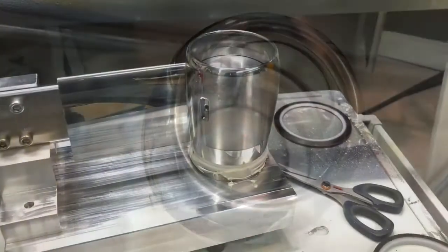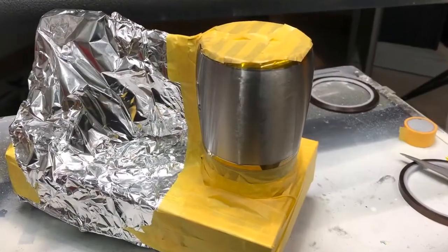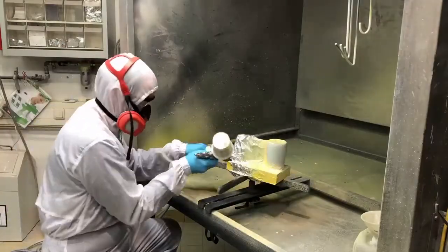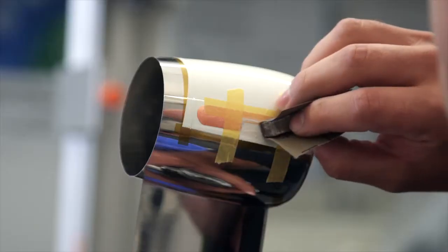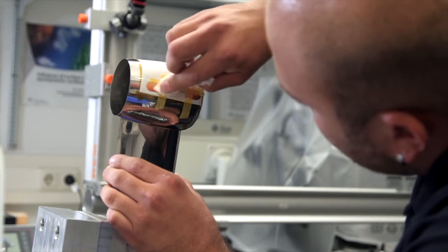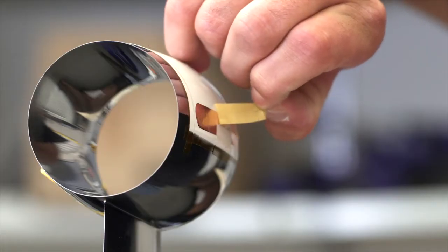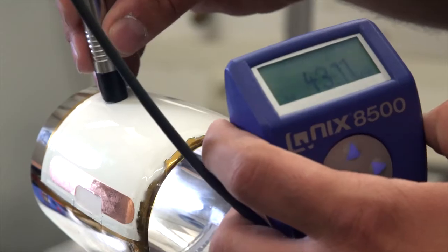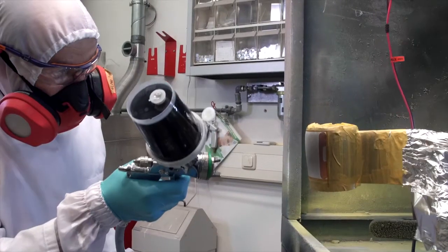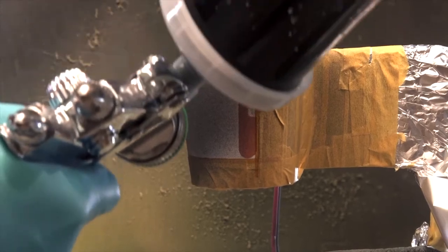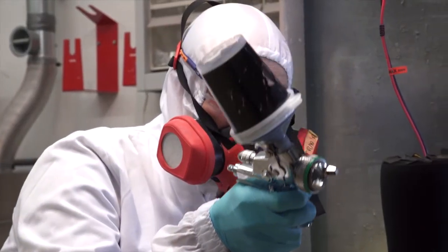Before entering the ETW tunnel, the most suitable measurement technique has to be proven within the pilot facility of ETW. A generic nacelle based on a two-dimensional profile with NLF technology was designed and manufactured. The different coatings as described above were applied, and the final polishing achieved a mirror-like surface with a surface roughness less than 0.02 microns.